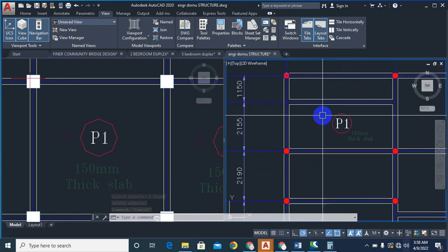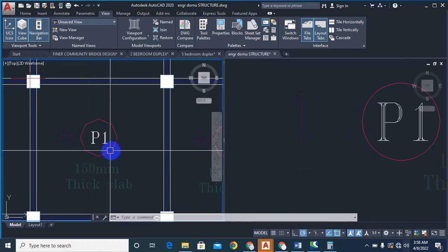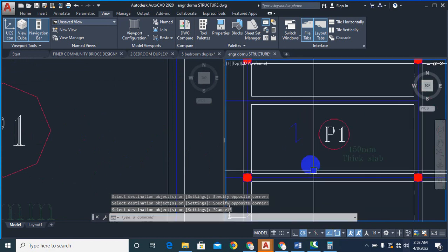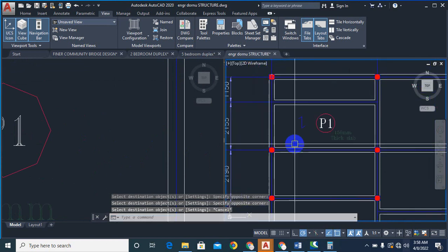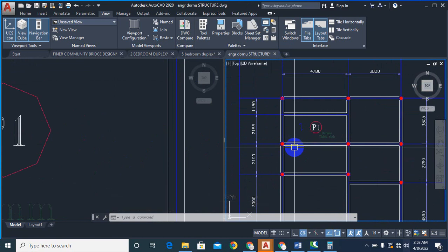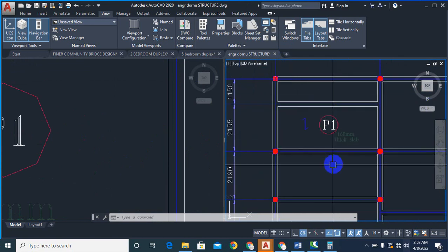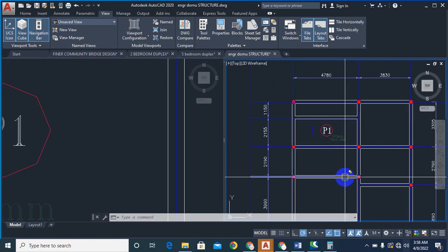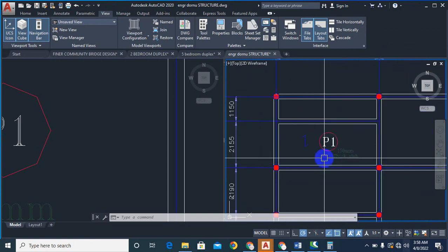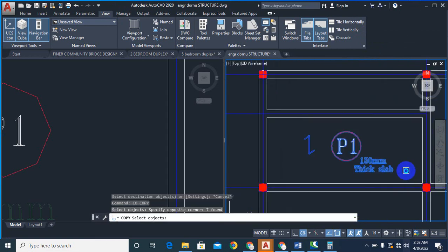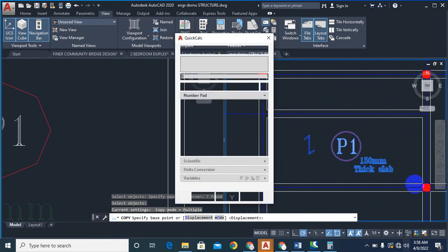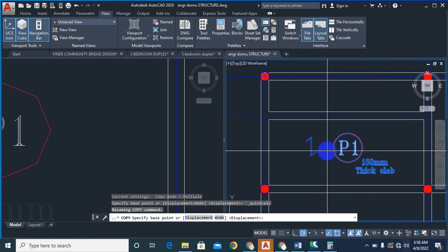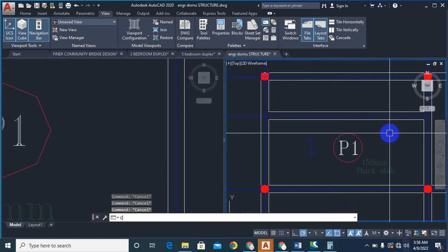Okay, so you can see how the indication is. Sorry, it's not very clear because of the color, so I'm going to change it to this color. I think you can see it clearly now. Okay, so this is a one-way slab. So you are going to be having your main reinforcement spanning going along this. This is now going to be a cantilever. Okay, around here is going to be cantilever.